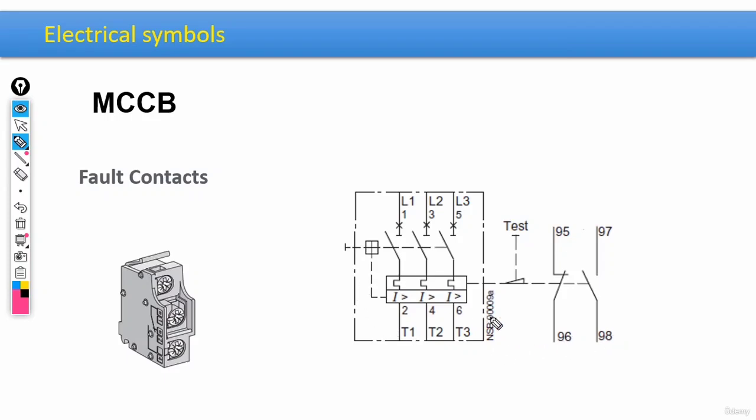And when the switch is set on trip, these would react. And you know the drill, basically. Normally closed ones would open and normally open ones would close. And by the way, guys, when it comes to using these in control circuits, these contacts could actually be connected to signal lamps to find out what exactly is going on with our breaker.